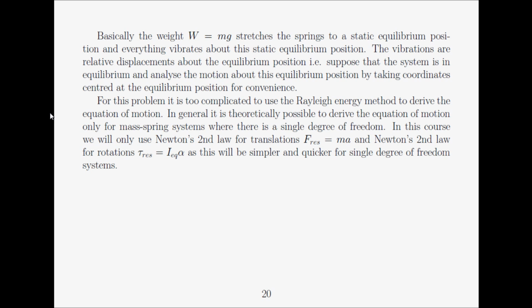The question also asked if we could solve the problem using Rayleigh's energy method. Technically, we could use Rayleigh's energy method. However, there are actually two subsystems in the main system. When I say two subsystems, it's because there are 2 degrees of freedom, an equation for theta, an equation for y. Both of these equations will have respective energy terms.